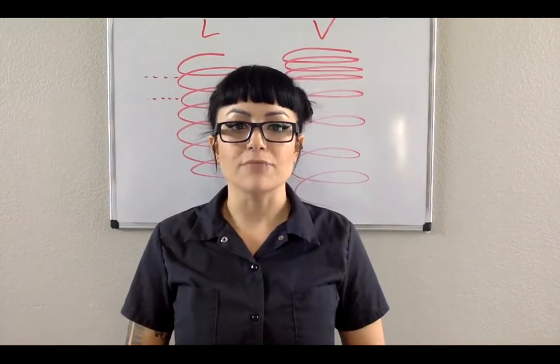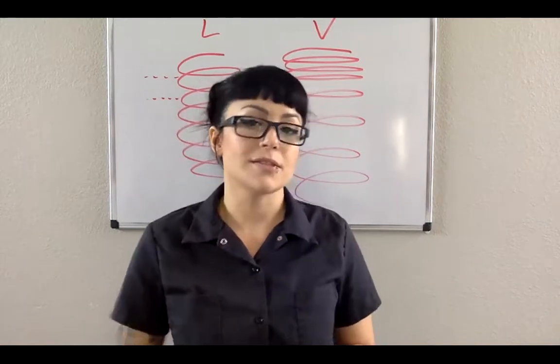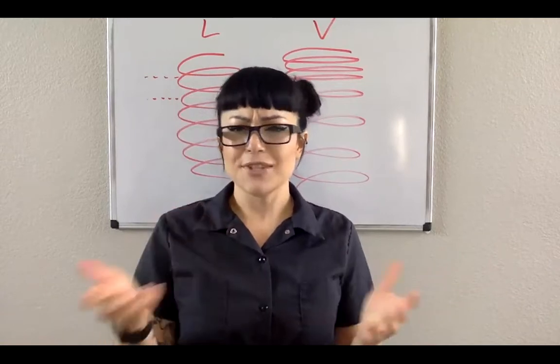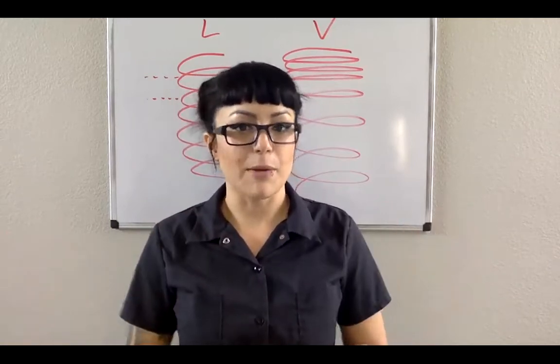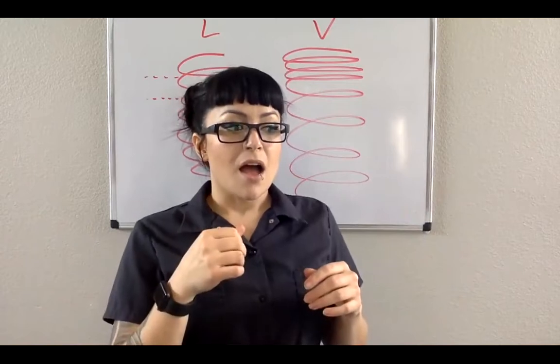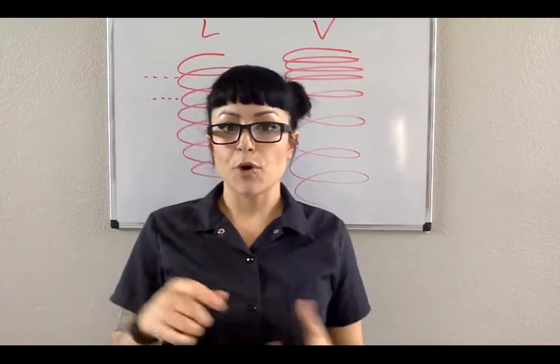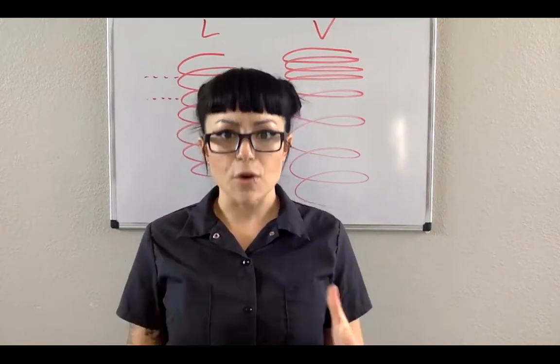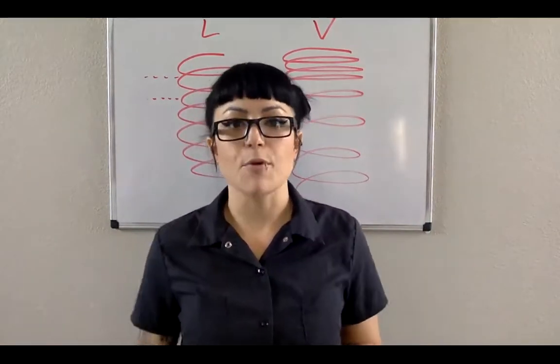I was hoping for a stiffer ride, at least for cornering, because at that time I was not concerned about comfort at all. I was 16, 17 years old. You're worried about performance. So as I started to get a little bit more aggressive with my driving, I noticed that these springs actually stiffen up in the corners. And that's when I learned about variable rate springs.